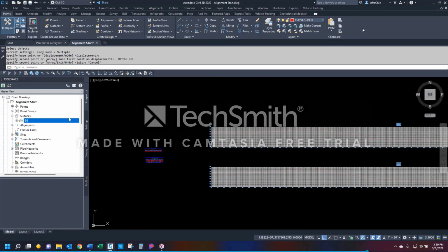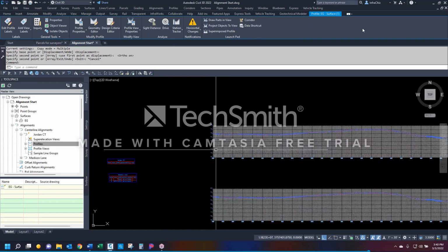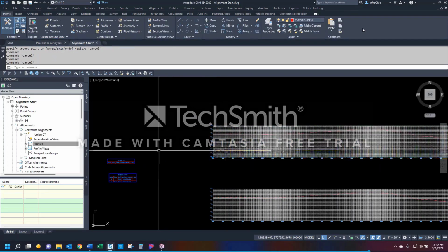Now I want to show you something. Over here in Tool Space, Alignments Collection, Center Line Alignments, we're on Jordan, and look at the little chevron that shows up. That means it's been active, it's got a profile, it's filled out, it's more than just an alignment. This is an alignment without a profile, nothing's been sampled, this has been sampled. Expand Jordan, we have 2 different sections, the profile, and the profile view. So the view is the grid.